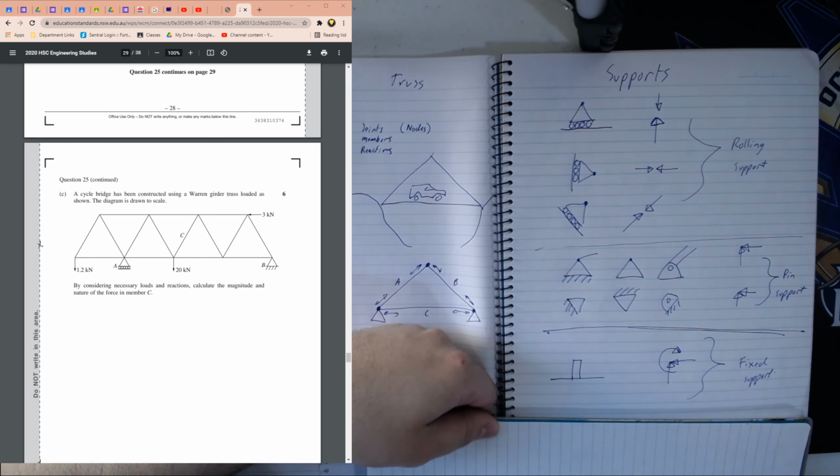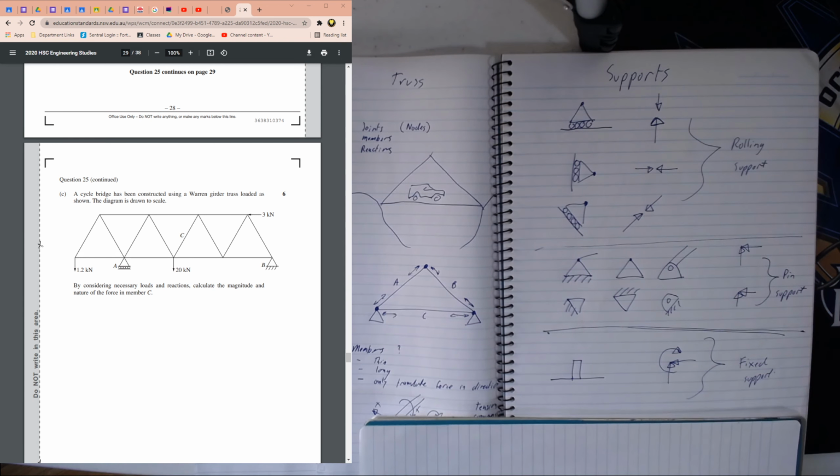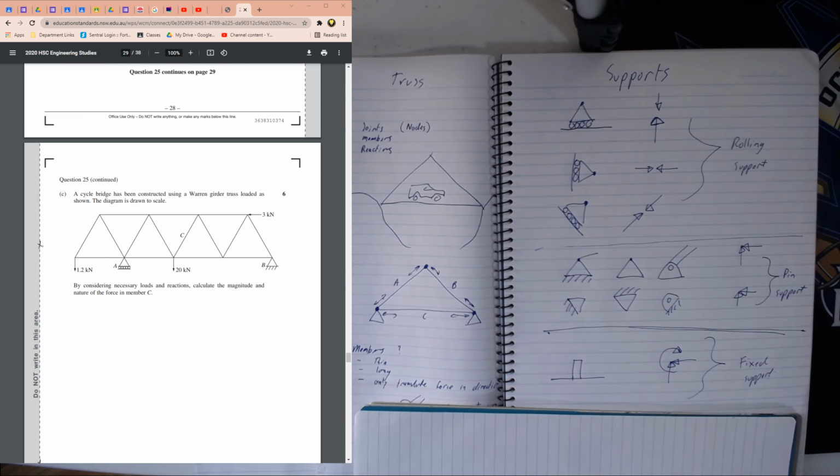We have things that are welded together or riveted together. But when we're solving truss analysis, we can still use fixed supports in our examples. Think of a fixed support like a flagpole wedged into the ground, nailed into the ground. That flagpole is able to provide force in the vertical and horizontal, but it's also going to stop rotation.